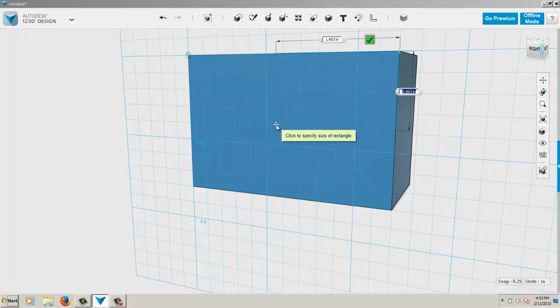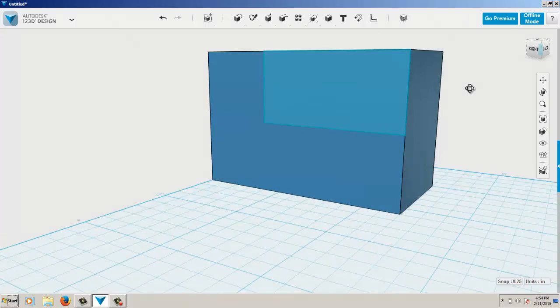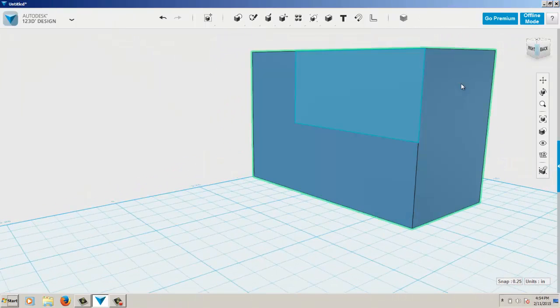I don't have to really worry about whether or not I get the right measurements, because you see there are 2 little boxes. The one that's for the 9.63 right now is your height, see? And the other one's your width this way, or length this way. So I know I need it to be 1 inch this way. I'm going to hit the tab key so I can highlight the one at the top. And I know that needs to be 2. I'll go ahead and hit enter, and then enter again. And that gives me another surface, another plane to make use of.